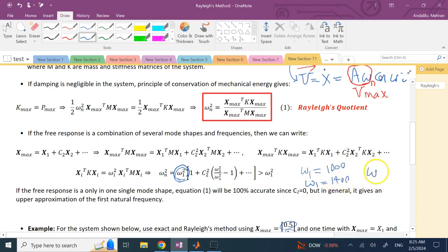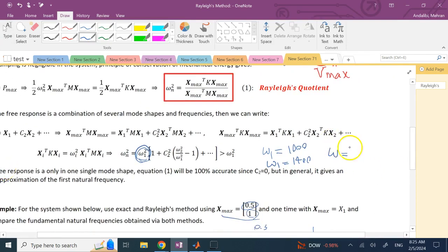So from here, you pick your operating frequency to be maybe what? Maybe, I don't know, 5000, 4000, 3000. But sometimes you don't want to go way above these numbers, so you just go to 1600. That's not really a safe thing to do, but let's say you don't want to go much higher than the natural frequency because it is high by itself. So here, because this is bigger than that and this is bigger than actual omega, I'm safe, right?